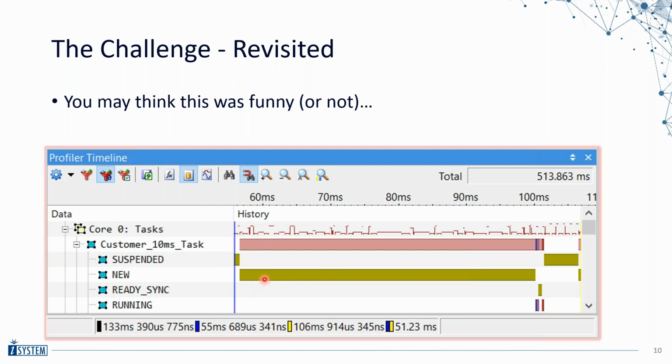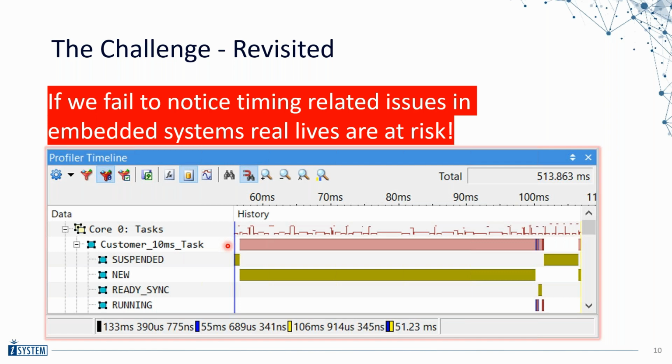So there should be a couple of other activations here every 10 milliseconds, but it's not actually executed. So the same type of behavior that happened on your desktop computer where WinIDEA did not get enough scheduling time and crashed, this can also happen in embedded applications.